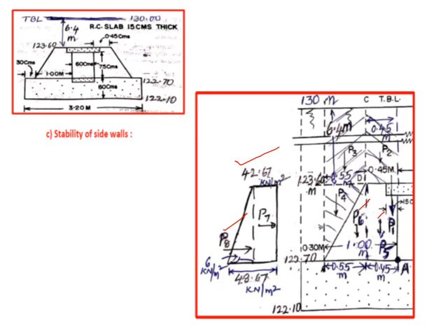P4, half into 0.55 into height 0.9 into 20, like that. So then what is P5? It is concrete. So 0.45 into 0.9 into 1 multiplied by 24, because it is concrete. Here half into 0.5 into 0.9 into 1 into 24, so multiplied by 24, that gives P6. So like this we are able to calculate it.